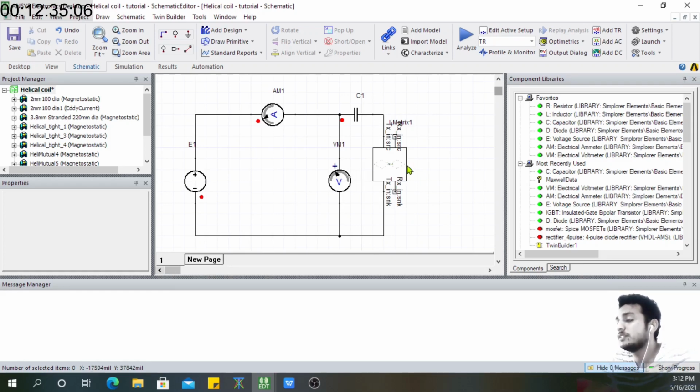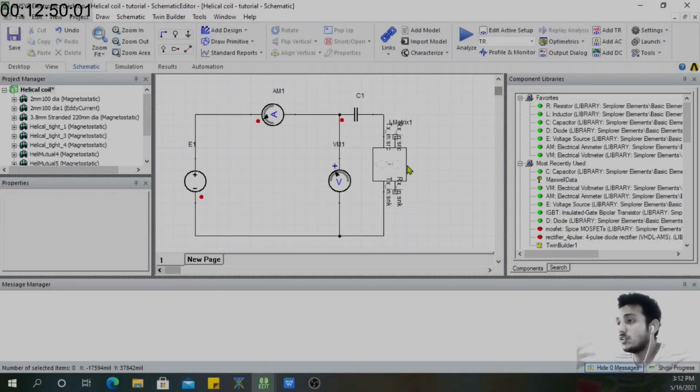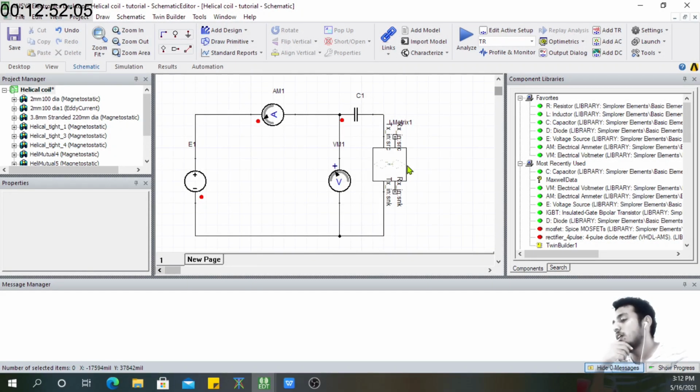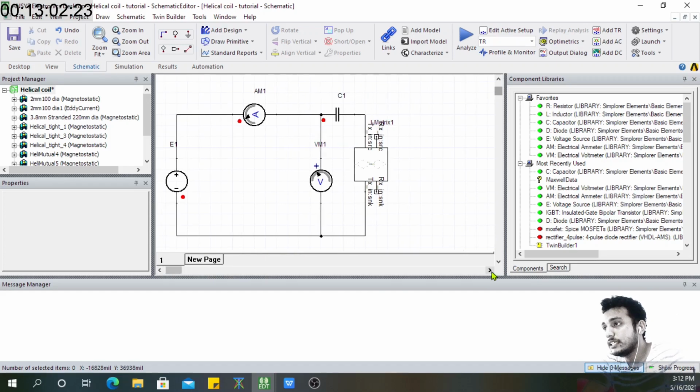Similarly, the secondary side will also resonate, and they will resonate at the same frequency. And when this happens, we can actually send power because of this phenomenon. We can transfer power from one end to another wirelessly. So there's a tight coupling, and it's called magnetic resonance coupling. So yeah, that's a simple fundamental thing that you need to understand about why we are using the series capacitor. So let's do this for the other side as well.